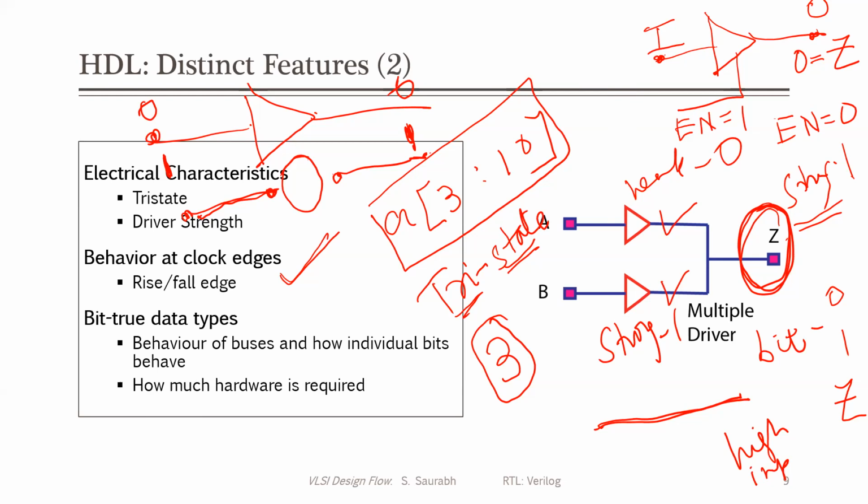But if you consider it at the circuit level, it may not actually be an infinite impedance. It will be high impedance, but may not be infinite. In an ideal case, an open circuit is an impedance of infinity, but that is an ideal case. In a real circuit, it will be very high, but it will not be infinity.